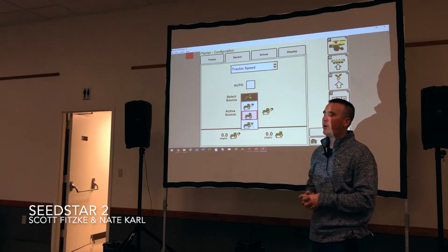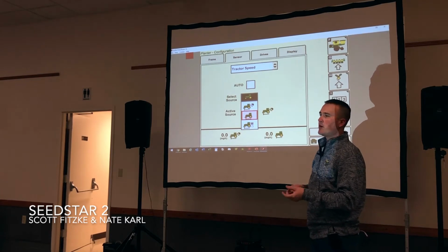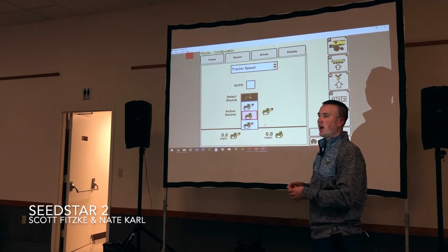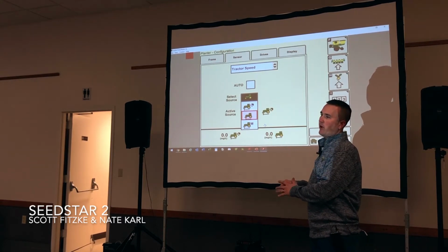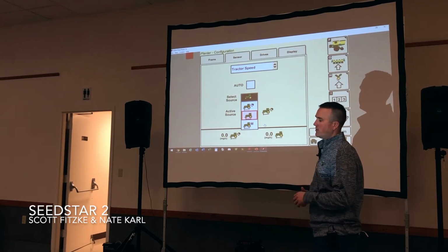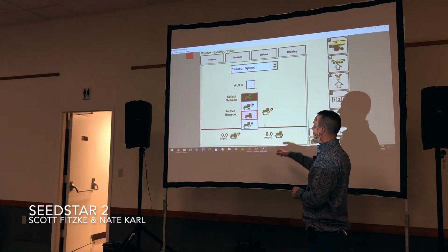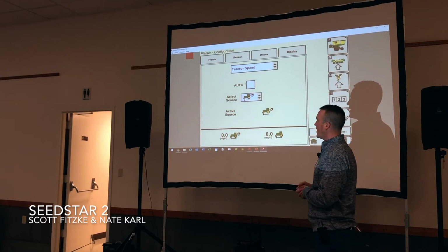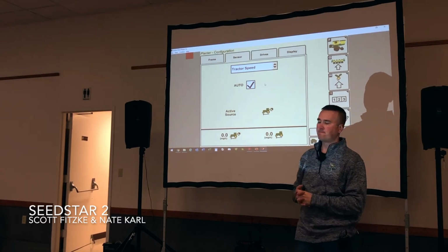And then also, depending on which series of tractor and how it's wired, will also determine which source it comes from. A lot of the tractors are pre-wired, but we can change a plug to pick from radar or GPS as the source. That would be determined by what model tractor and year it is. Most of the time, we're just going to leave that in auto, and it's going to pick the best, most reliable source for us.